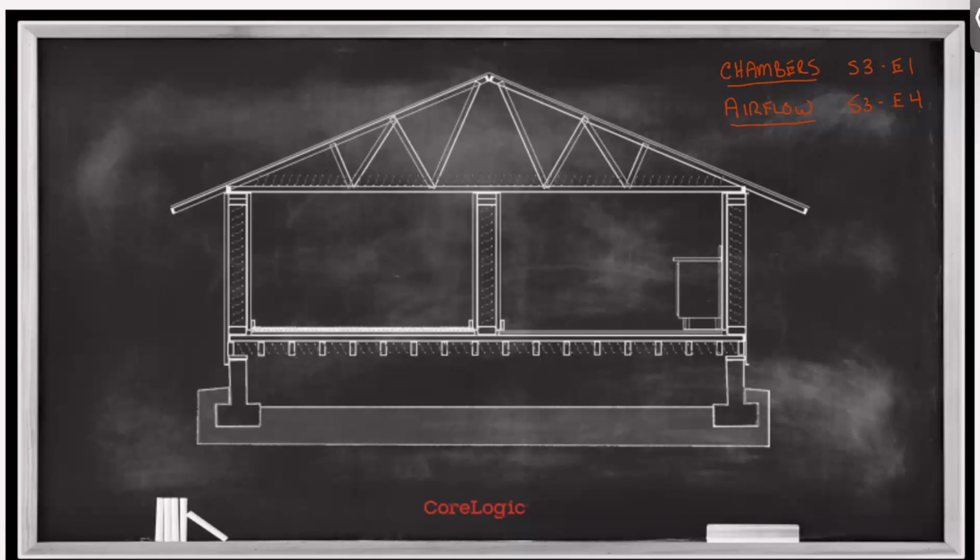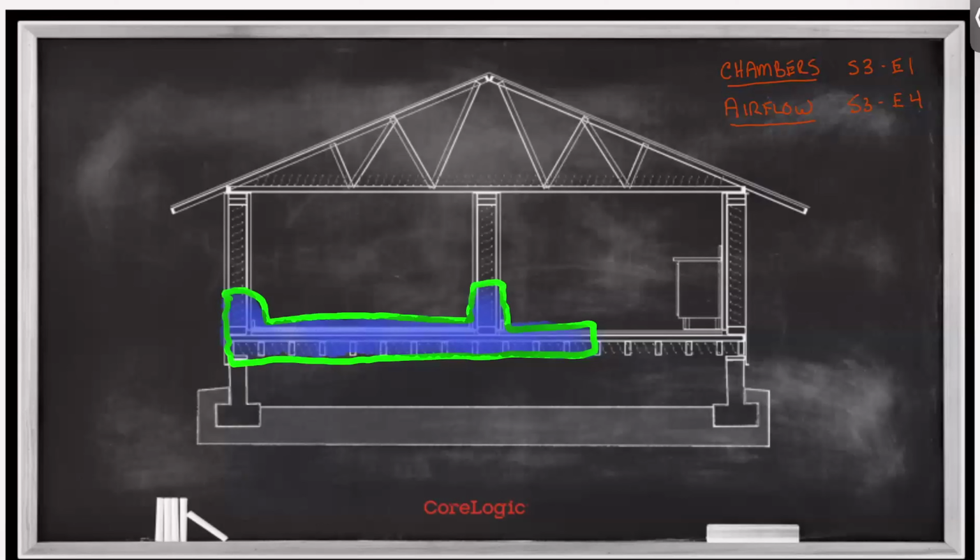When we're dealing with moisture in an environment and that moisture has affected particular materials within my drying space, when we want to establish humidity control, we first need to establish the chamber we're going to control the humidity in. And by chamber, what I mean is that we have to define the outer limit of the affected area, right? So here I've drawn out that we have all of this affected within the space. This is my water migration.